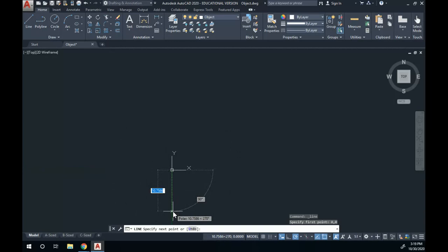It's showing on AutoCAD 90. AutoCAD will only measure the angles with respect to up to 180 degrees. Or you can think of that as negative 90, however you want to look at it. And then 360 is back to where it began. So it's only going to show it for vertical and horizontal angles as I move around. So it just helps you align your cursor as you make your lines. Makes it a little bit easier.